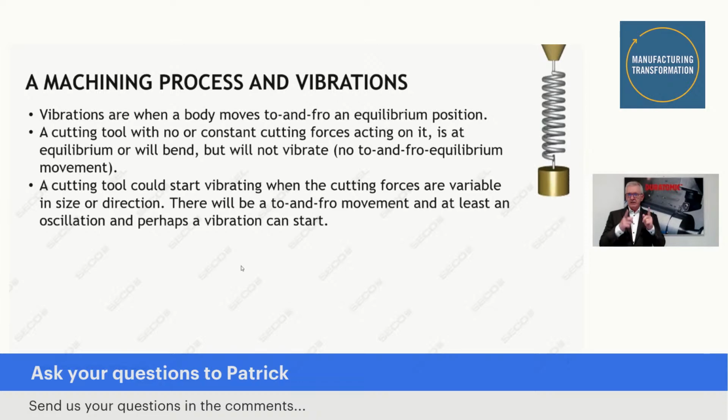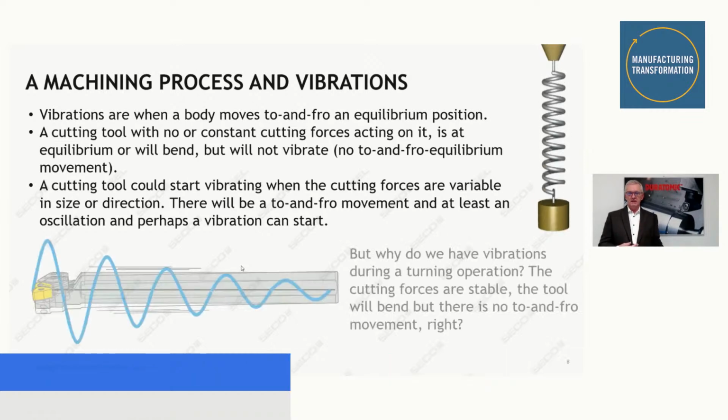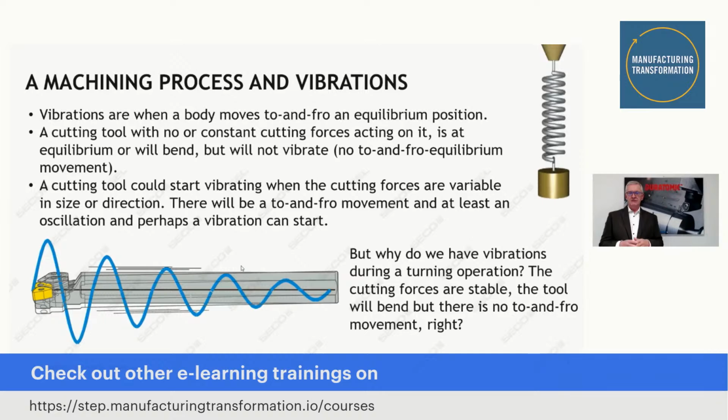A cutting tool will only vibrate, or could start vibrating, when cutting forces are variable. Change in size or change in direction. Because then we will have a to and from movement, and a vibration could start. Now, that's very briefly some physical background.